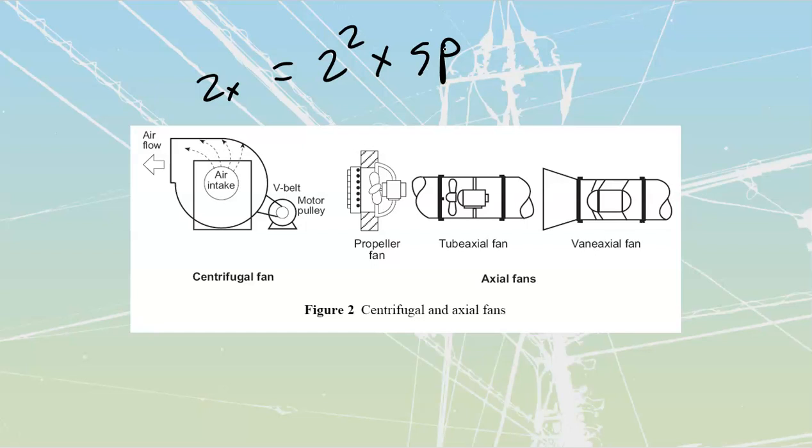You end up with this noise. Everybody's heard that inside of buildings, those creaking, metallic clunking sounds of ducts expanding and contracting. Power is going to vary with the cube of the fan speed. So if you double your speed, 2x speed, which got you 4 times the static pressure, you need to have 8 times the horsepower.